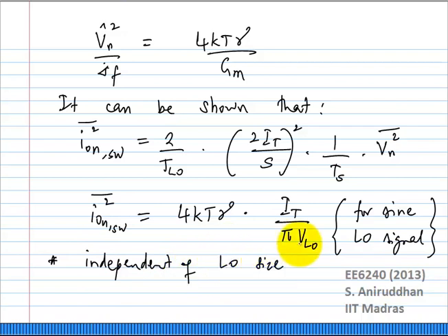This is because, I think we touched upon this yesterday when you were asking why it does not add broadband noise. So in reality, if you actually try to make the device switch faster by increasing the device size, what happens is this value drops because the large signal GM, the piecewise linear GM that you have derived, becomes larger, and therefore Vn squared actually becomes smaller.